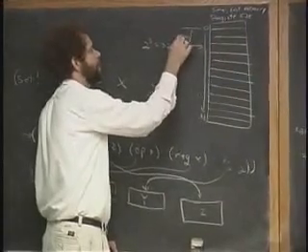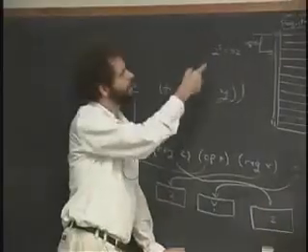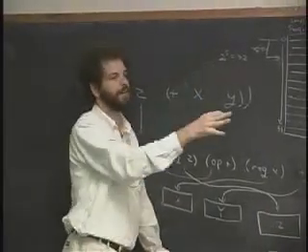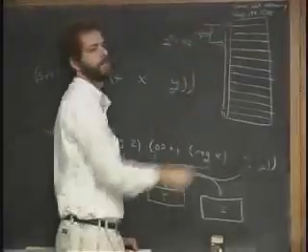I put in a 5-bit number here. This is a way you write 5 bits. You have a line, slash through it, and the number 5. That means 5 wires that go in, 5 bits. That's enough to select any of the 32 slots that are here.